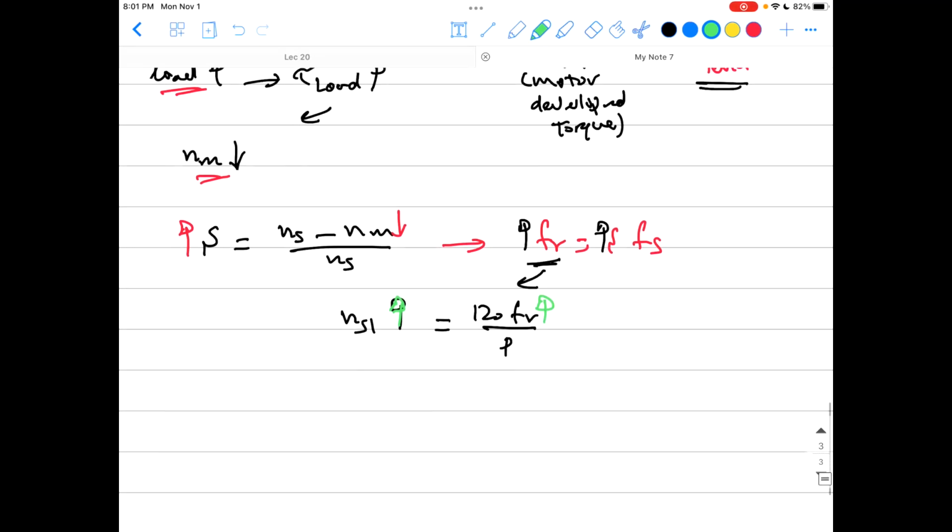Okay, guys? Remember, the speed of rotor field equals Nm plus N slip: the mechanical speed of the rotor, which carries a magnetic field, and the speed of the magnetic field of the rotor itself with respect to the rotor body, of course.